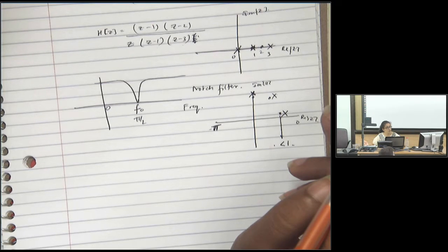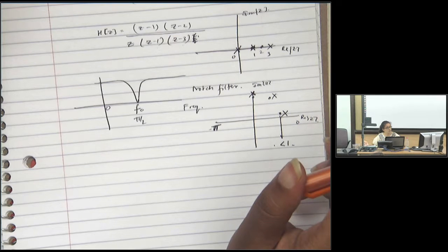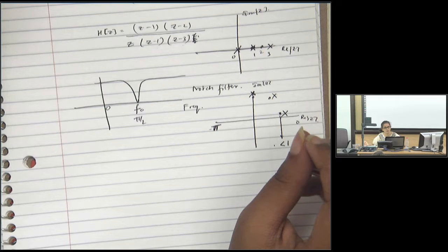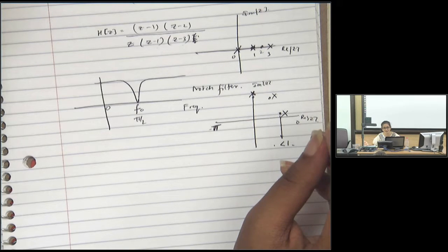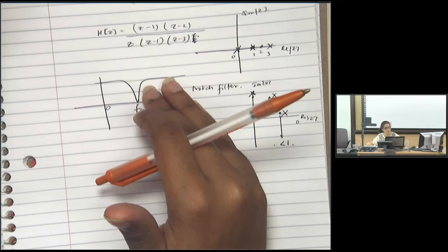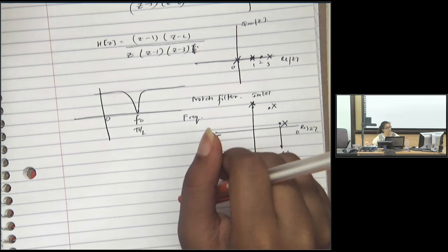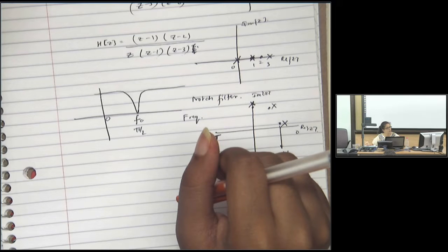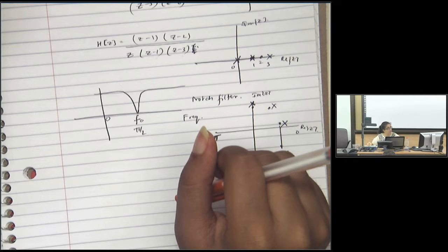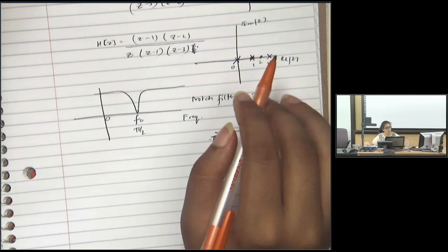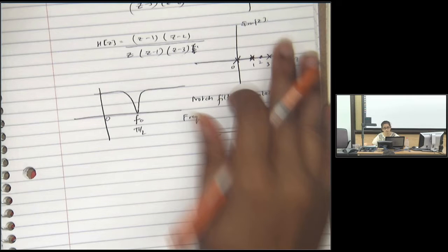If something cancels, do we cancel it and then do that, or do we not cancel it? I noticed in exams, you usually only ask about BIBO. Yes, because obviously there's a confusion between BIBO and asymptotic. For asymptotic, you have to assume that it's the characteristic equation, because you don't know if it's already been simplified. So keep it as is without simplifying and then find the stability. If you're finding h of z and h of s, that's the way to go. But if it's given to you, then assume that the denominator is the characteristic equation and go forward.